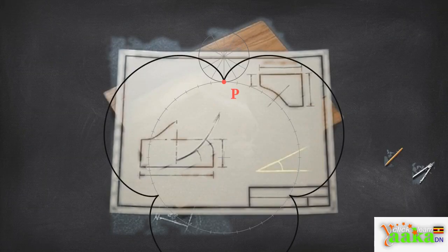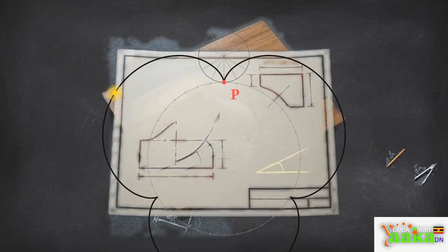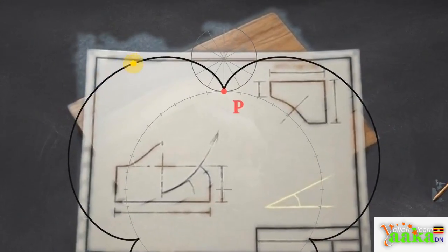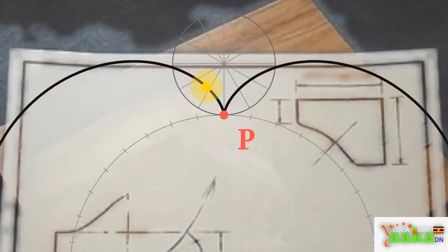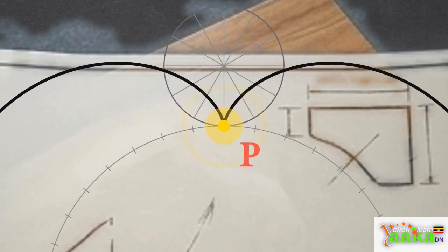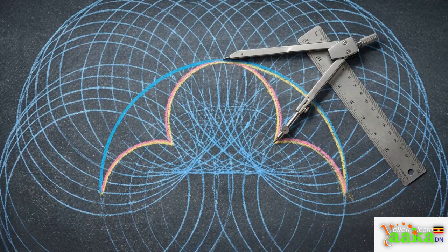Inspect your final drawing. Check the starting point P. If your construction spacing was accurate, your bold curve will return perfectly to that starting tangent point after the 12th division. Take a look at this completed drawing.